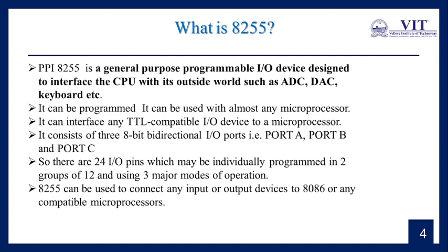So it is a programmable IC. It could be used for the outside world, where you have analog to digital converter, digital to analog converter, keyboard, and other sensors and so on. This 8255 can be programmed, or configured, in different modes, and it can be connected with almost any microprocessor, or any TTL compatible devices.